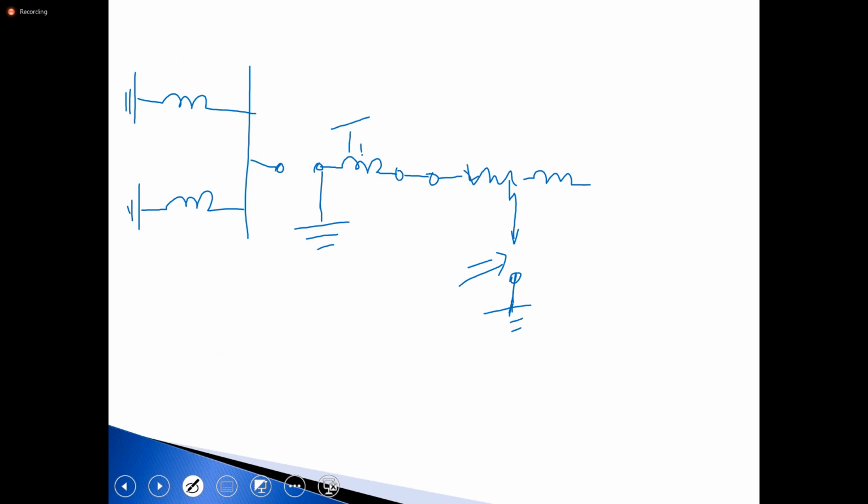So this is T1, this is L, or L over 2. On this side, I close A, all right? I then put in the zero sequence for the transformer, but I also put in the 3Zn. I have only turned it because I've run out of space, all right?